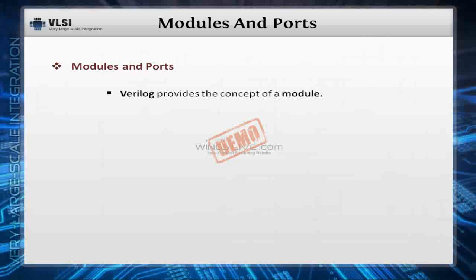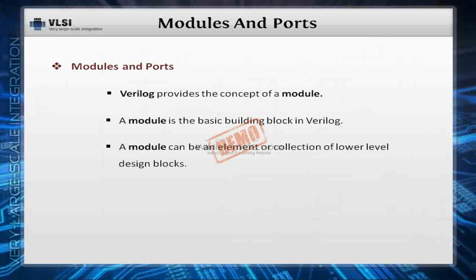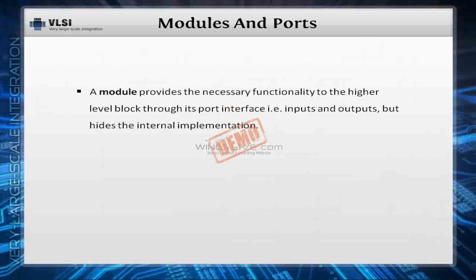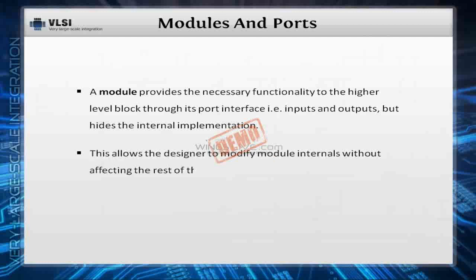Verilog provides the concept of a module. A module is the basic building block in Verilog. A module can be an element or a collection of lower-level design blocks. Normally, elements are grouped into modules to provide common functionality that is used at many places in the design. A module provides the necessary functionality to the higher-level block through its port interface, that is, inputs and outputs, but hides the internal implementation. This allows the designer to modify a module's internals without affecting the rest of the design.